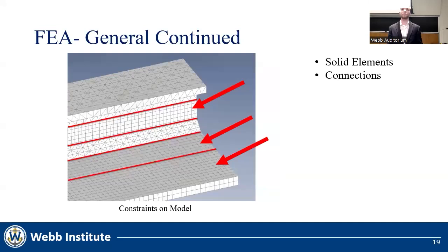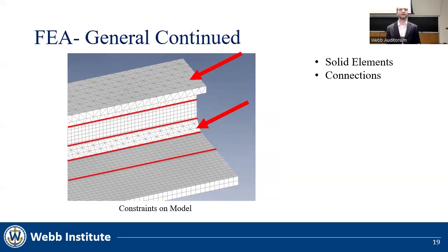The plate and the lower part of the stiffener were modeled using hex and wedge elements, while the weld bead and the stiffener flange were modeled with the TET elements. Von Mises stress was analyzed as opposed to Tresca stress because Tresca stress tends to be more conservative, and we are prioritizing accuracy since we are testing to failure.